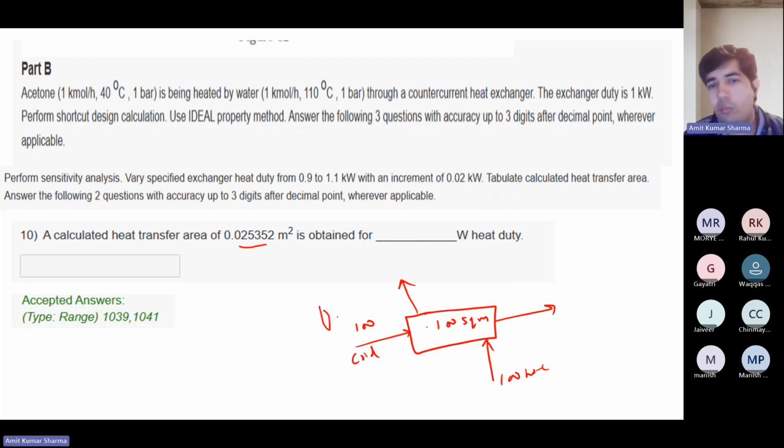So with this configuration, suppose I'm getting a heat duty of maybe 10 kilowatt. Now if I increase the flow of the cold fluid and the hot fluid remains the same, suppose it becomes 150. Now what will happen? Will the area change? Area will not change. Practically the heat exchanger design is completely fixed, because we have already specified everything. Design is same.